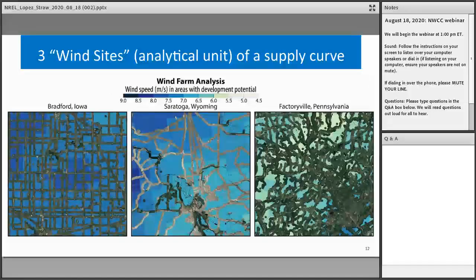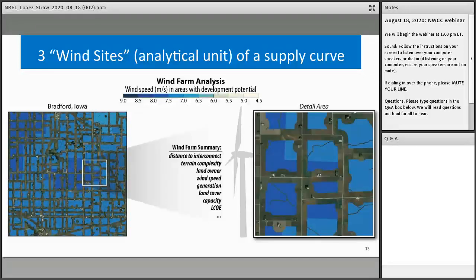The land suitability is combined with wind resource. Our wind resource is represented by the Wind Toolkit, a data set based on numerical weather prediction using the WRF Model. As I said earlier, the Wind Toolkit has 2 kilometer spatial resolution with hourly temporal resolution at multiple hub heights, and is actually an open database that's open to the public. In fact, while REV uses only hourly resolution, the Wind Toolkit has a temporal resolution that goes down to 5-minute increments.